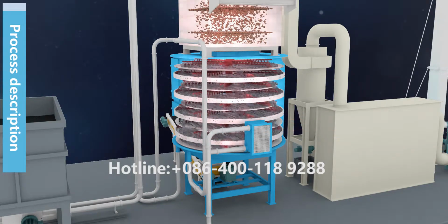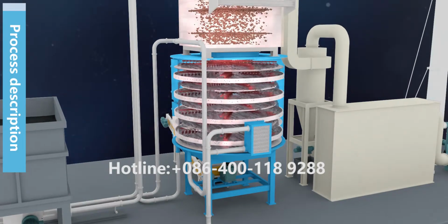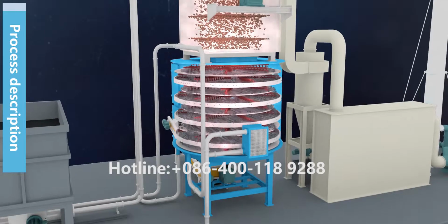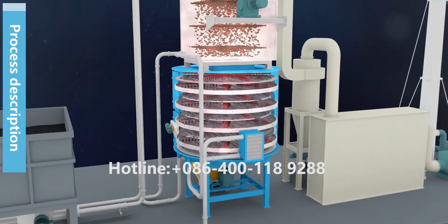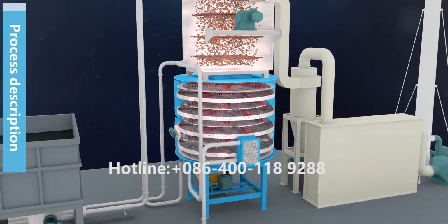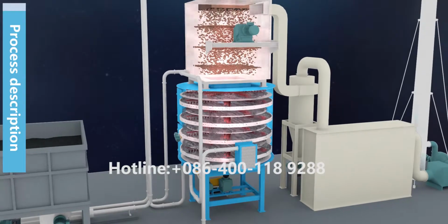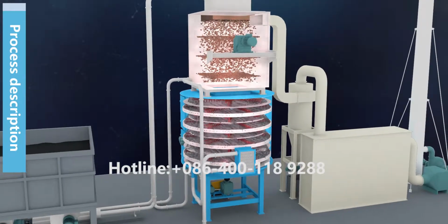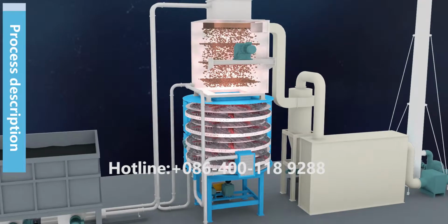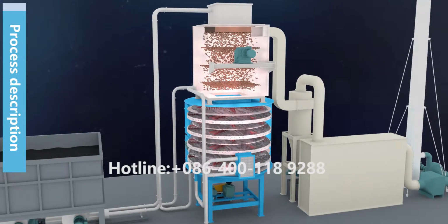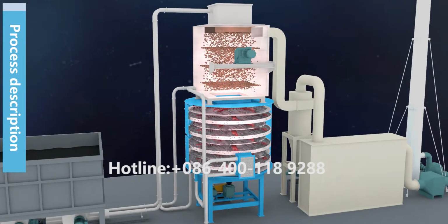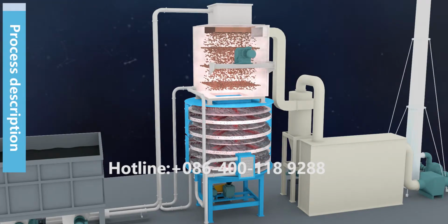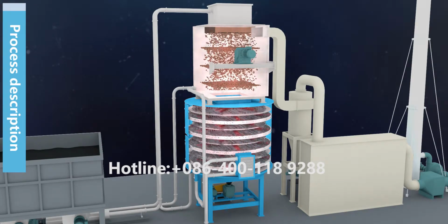During the granulation and drying process, the heat exchange consists of three types of heat transfer: convection, radiation, and conduction. The sludge moves down and the hot air flows up, providing excellent heat exchange. The dust can be conglutinated by the wet sludge before the off gas is discharged, reducing the dust quantity in the off gas.